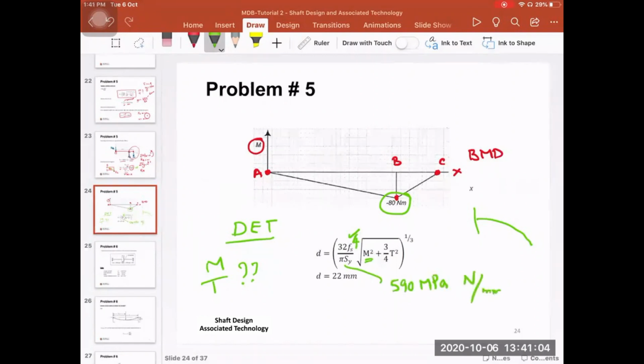That's why I was saying that I like this combination of units, because it doesn't make any problems. So any forces in Newton, any dimension in mm, any stress or strength or elastic modulus in megapascal. Then you just apply here or just substitute the value of the torque and the moment that we had, and then the diameter of the shaft can be found.